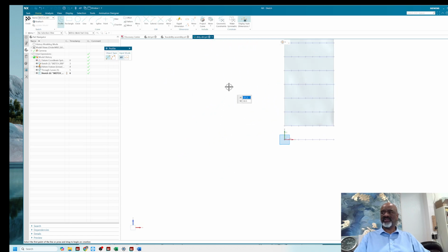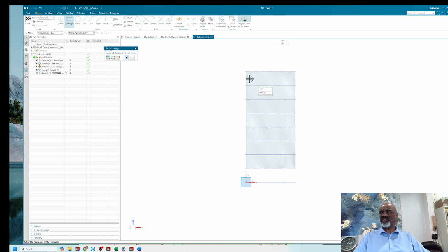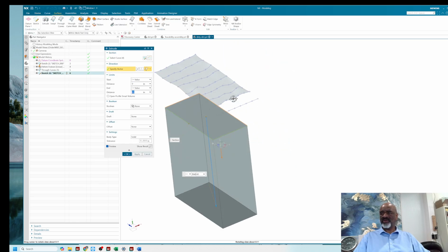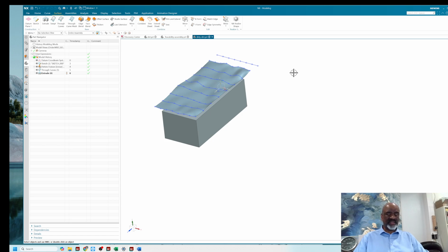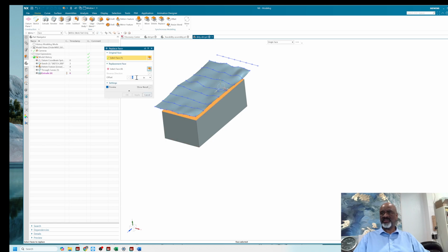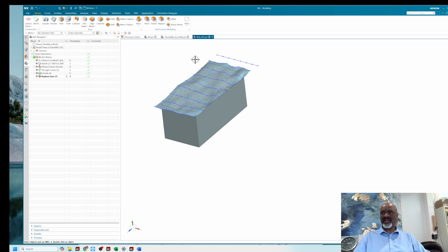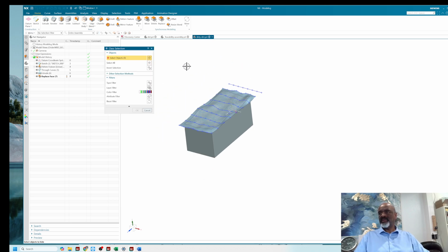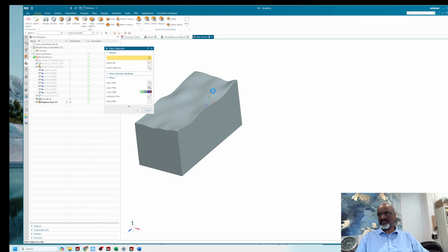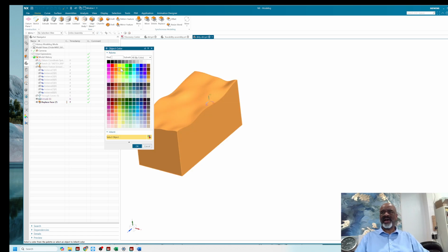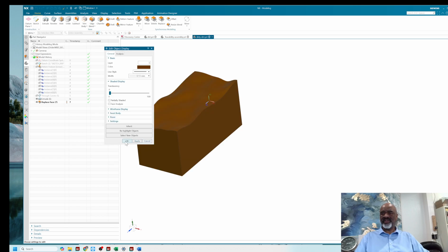And finally, I'm going to make a square or rectangular kind of patch of this, and I'm going to extrude that up this way, like so. And then finally, I want to go into synchronous modeling off the Home tab and do a replace face. So this face is going to be replaced with this one. Say OK. Control B. Select it all like this. Hold my finger on the Shift key on the sample. Say OK. And Control J. And there you have a model of the dirt.